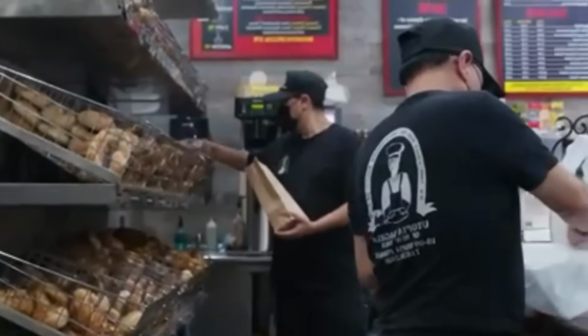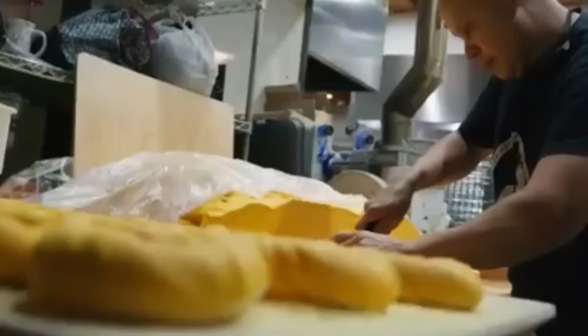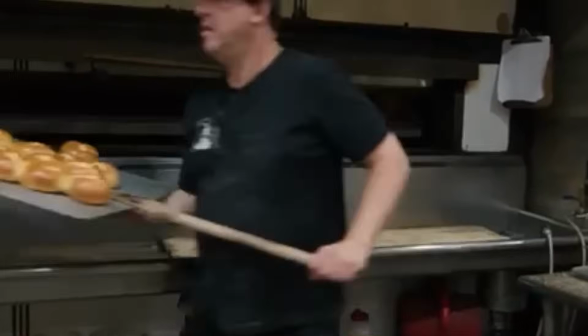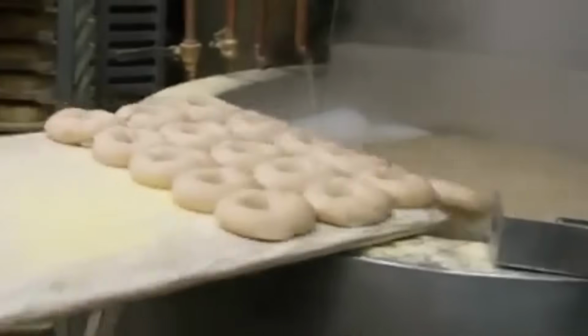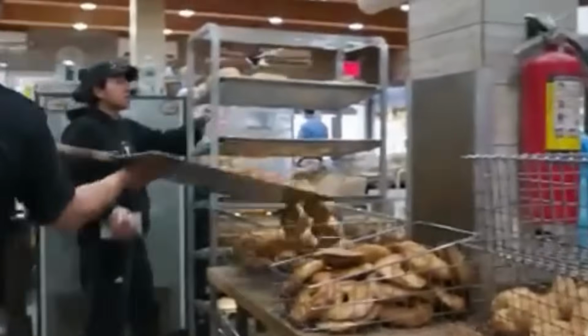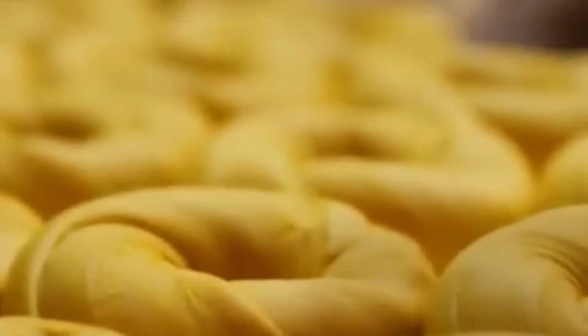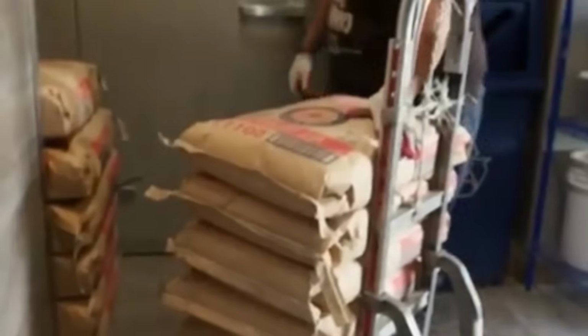What follows is the defining characteristic of bagel production: boiling, or more accurately, a high-temperature water bath that sets the outer crust before baking begins. As the proofed bagels exit the chamber, they move onto a boiling belt that carries them through a long stainless steel trough filled with circulating water, often mixed with barley malt or a similar solution to enhance browning later in the oven.